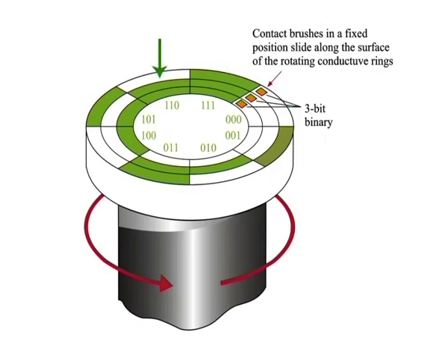The more sectors there are, the more accurately the position can be represented, but we are using only 8 for purpose of illustration. Each sector of each ring is fixed at either a high level or a low level voltage to represent ones and zeros. A 1 is indicated by a colored sector and a 0 by a white sector.